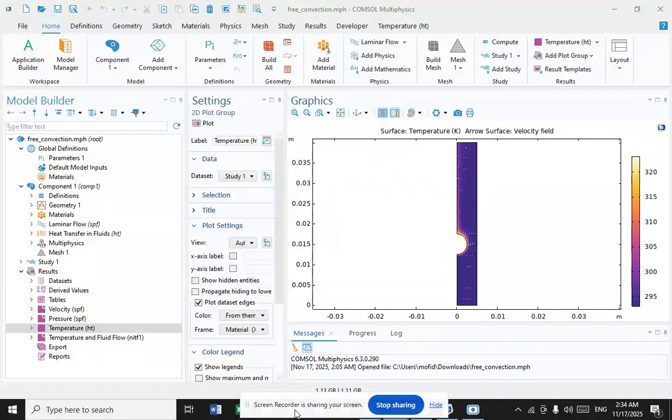As a consequence of this, natural convection heat transfer rates will be lower than forced convection in a particular situation if all other controlling variables like temperature difference, geometry, and medium are the same. Recall that traditionally, convection aided by an external agency like a pump or fan or blower has come to be known as forced convection. In view of this, natural convection, where there is no forcing by an external agency, so to speak, is also known as free convection.